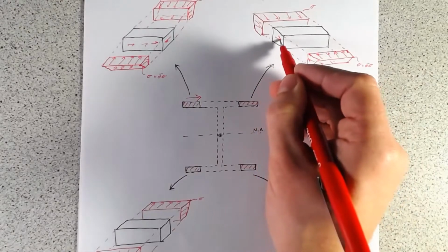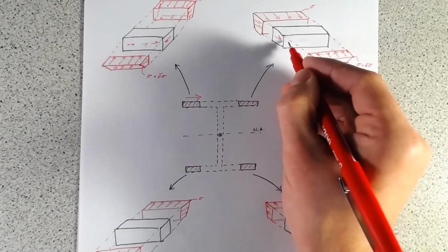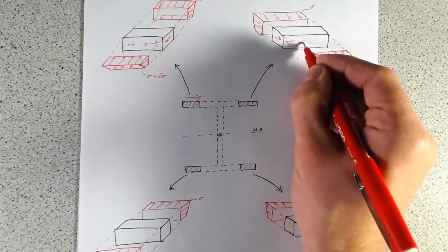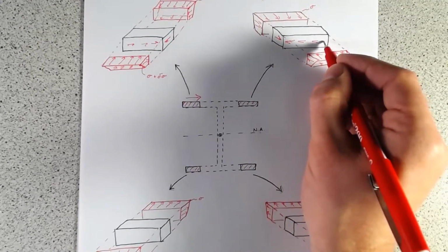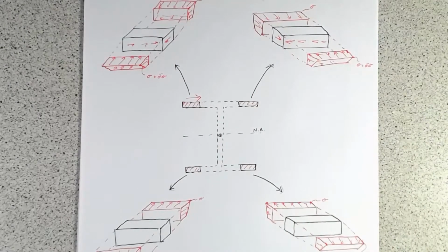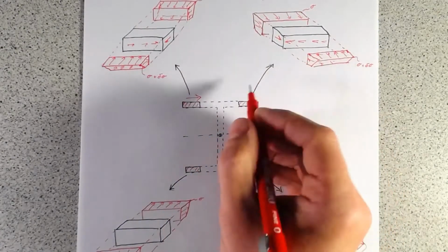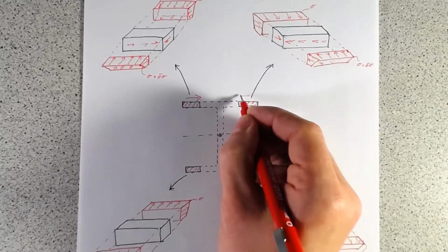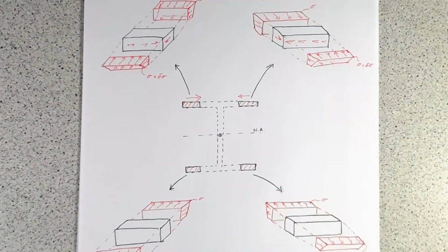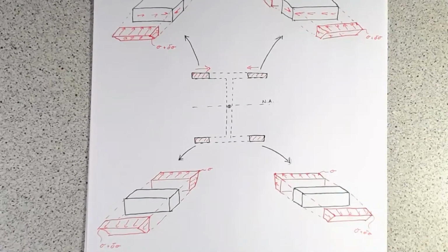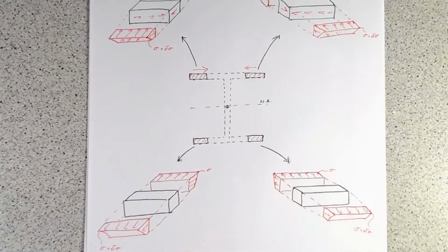And because we need to have our corners in equilibrium, just remember our arrows for shear always point towards arrows. Tails always point towards tails. So this means that our shear stress, or shear flow, in the other flange is also going to go towards the web. Well, now let's look at the tension side.